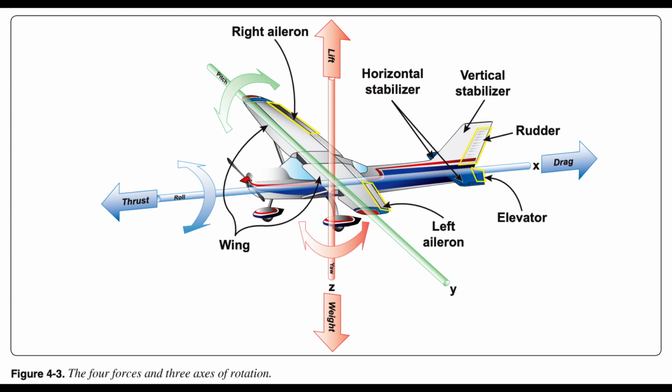Parasite drag. Parasite drag is all drag not caused from the production of lift. Parasite drag is created by displacement of air by the aircraft, turbulence generated by the airfoil, and the hindrance of airflow as it passes over the surface of the aircraft or components. All of these forces create drag not from the production of lift, but the movement of an object through an air mass. Parasite drag increases with speed and includes skin friction drag, interference drag, and form drag. Skin friction drag.